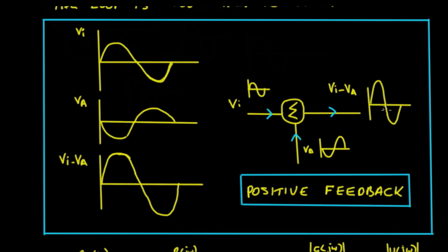So it means that if we feed that back again at this frequency here, we're going to get an even bigger signal. And so if we feed it back and the feedback loop continues, what's going to happen is we're going to get a huge signal coming out here at this frequency. So it means that at this frequency the op-amp doesn't work, okay?